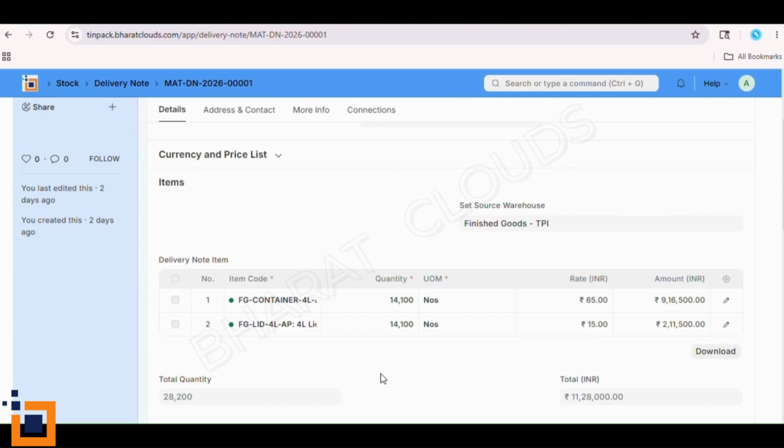Second, manufacturing scrap. Every operation produced slightly fewer good pieces than it received. Across 5 operations on the body line, the cumulative yield was about 94%. Both of these, incoming quality rejections and in-process scrap, are tracked automatically. The system doesn't hide the shortfall or let anyone fudge the numbers. 15,000 was ordered, 14,100 was produced, 14,100 was delivered. The gap is explained, documented, and traceable.